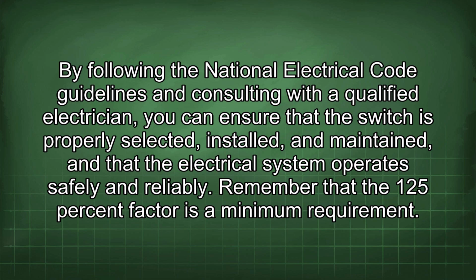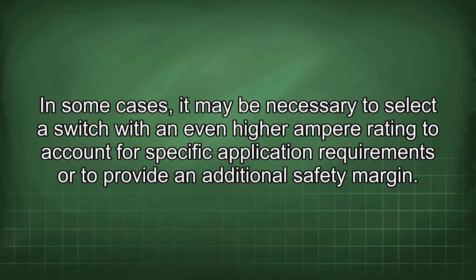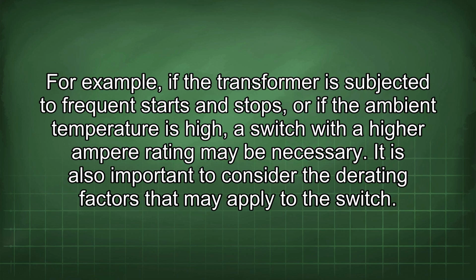Remember that the 125% factor is a minimum requirement. In some cases, it may be necessary to select a switch with an even higher ampere rating to account for specific application requirements or to provide an additional safety margin. For example, if the transformer is subjected to frequent starts and stops, or if the ambient temperature is high, a switch with a higher ampere rating may be necessary.